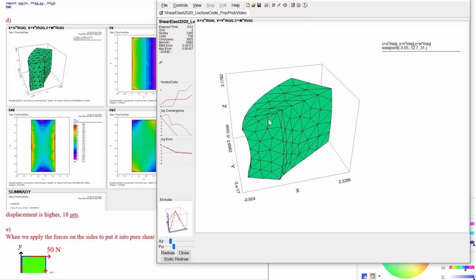So this is not what I expected. I expected when you pulled on it there and got it to bend, it would attempt to buckle in the opposite direction. But here the displacement is so low that we're just applying this compressive force on the right, and that gets it to expand over there, and tensile force on the left, and that requires compression, meaning that the wall anchor, other things equal, would tend, at least at first, to buckle kind of the other way.